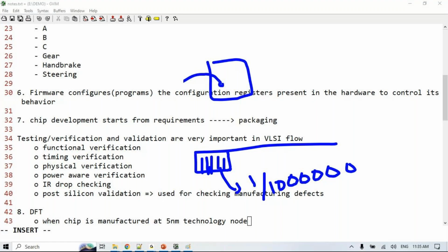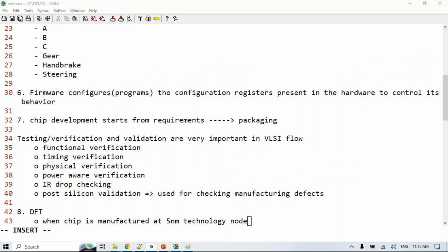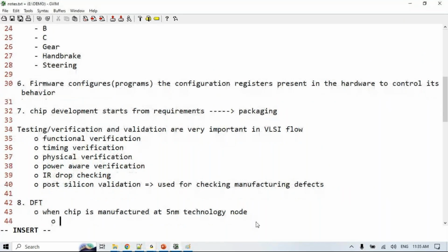I'm telling you there are different reasons why one chip may work and one chip may not work. A company, let's say TSMC, will develop a process in such a way that dust particles don't go in. But still, whatever they do, out of 100 chips, some chips will definitely fail. Why will they fail? Mostly because of manufacturing defects. So manufacturing defects are of a few types.